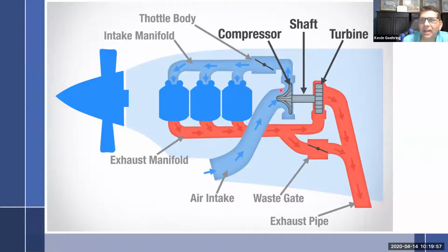Then alongside of that, of course, you just speed it up and you can live with the manifold pressure you got there. Or if it's too high, then you back this off. Or if you back that off, then you can lose a little bit here. If you lose a little bit here, you're going to lose it there. And then your speed starts falling off. And so you start chasing this around. So there's this whole problem with turbochargers hunting back and forth.